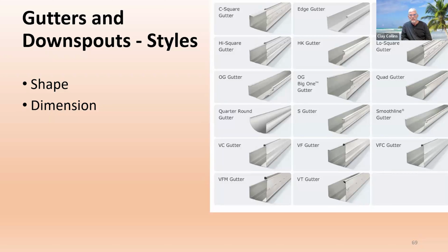If there are trees and no excluder, you can pretty much guarantee that your gutter's going to be blocked. And when I'm up there on the ladder, on the roof, I'll take a picture of it, but I'll also reach in and take out several handfuls and take pictures of that and show the client, if they're there, just what we're pulling out of there, to show them that there is a necessity to do some cleaning.